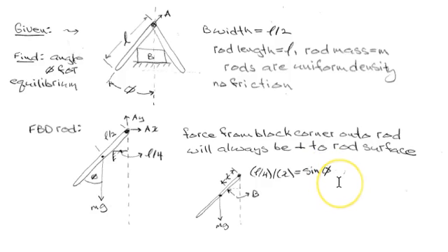So I should be able to use the sum of the moments around A to get B, given that I know it's acting perpendicular to the rod, and I have enough geometry to relate its application position x to position A.